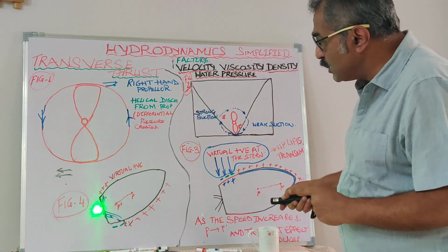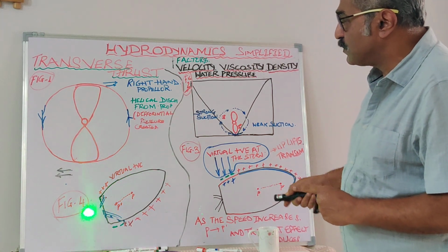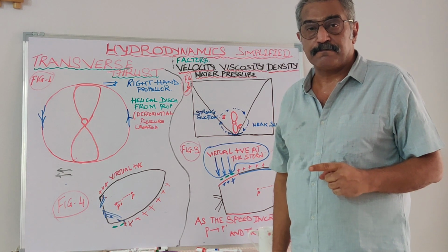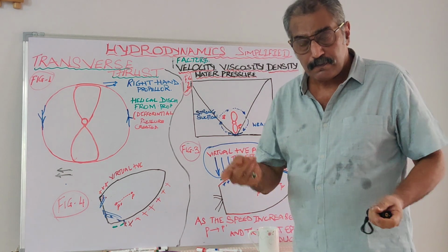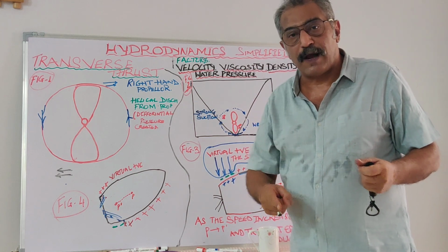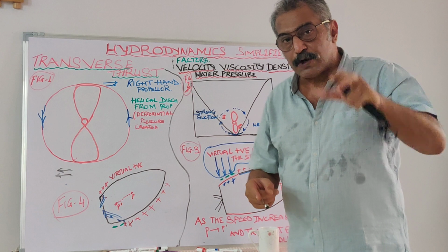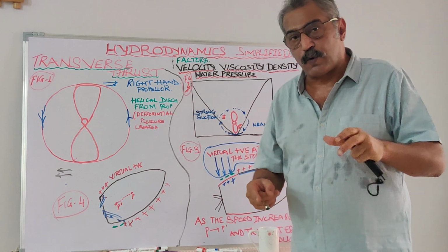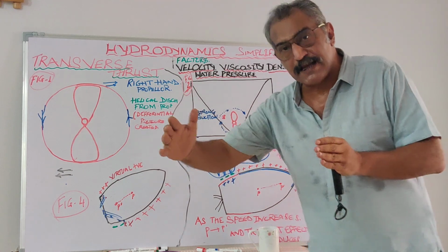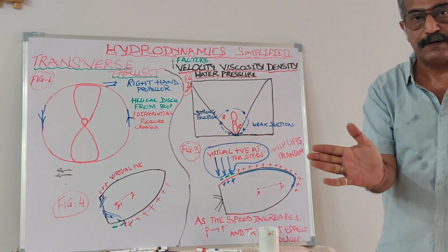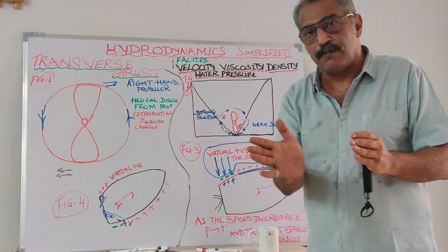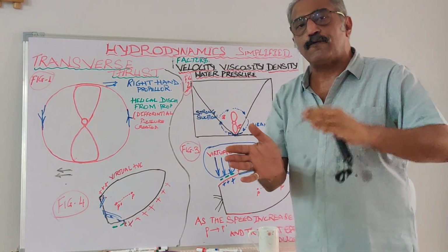Likewise, a virtual positive force is also created on the transom, on the port side. When the propeller is turning anti-clockwise, the virtual positive forces generated on the port quarter are also facilitating, because the water is getting filled up as the vessel is canting to starboard. So whatever vacuum is created because of the underwater volume of displacement is also getting filled.